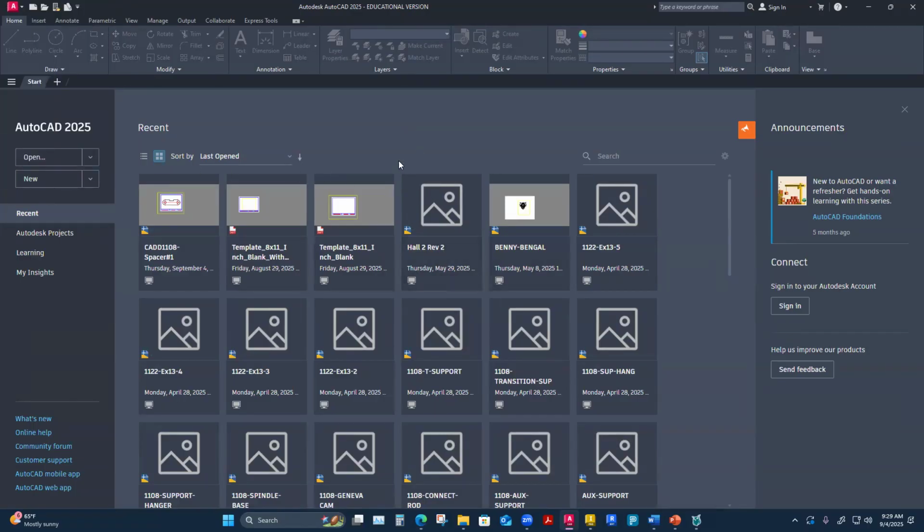We talked about the start menu, so I'm going to go into the drawing menu and keep going from there. How I went into that was I just pushed the plus button here, which is a quick way to create a new drawing. I'm really not specifying a format or anything, so it might not always be the ideal way to start a new drawing. I may actually want to choose a template. I think yesterday I talked about there being four different places I can choose to start a new drawing and from a template.